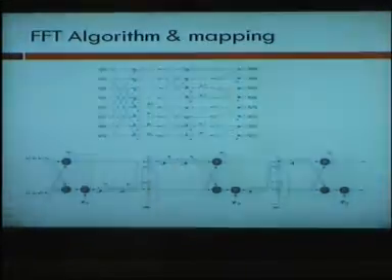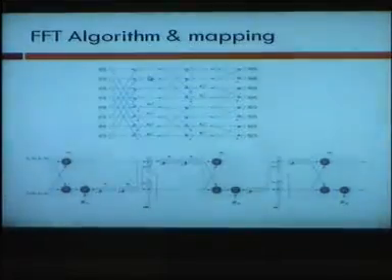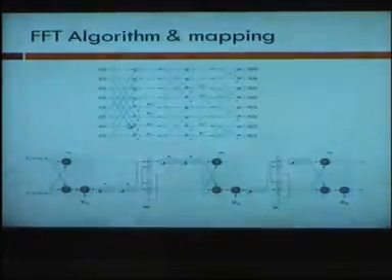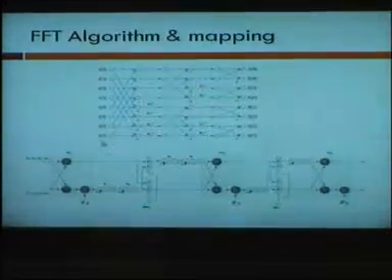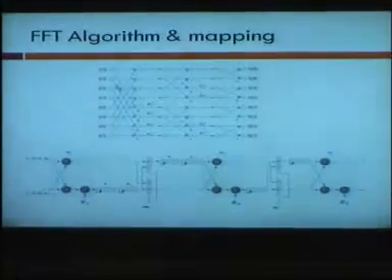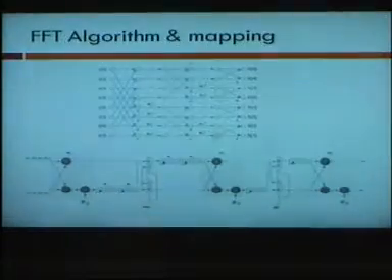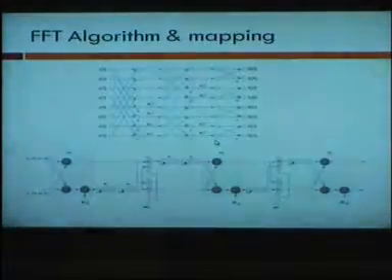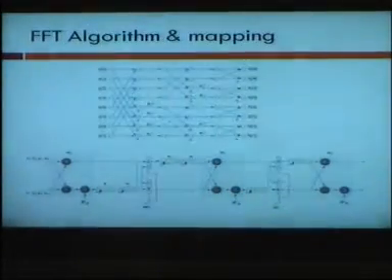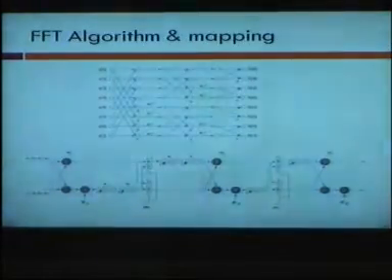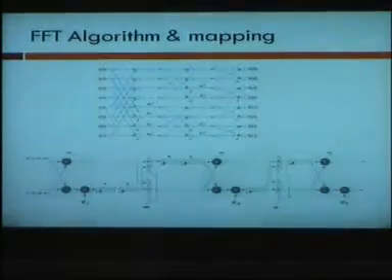So this is a flow graph of the fast Fourier transform, and this is a hardware implementation. It's a very interesting, not very easy to conceive design, where if you count, these are 1, 2, 3, 4 butterflies. And in every stage you have 4 butterflies. So if you're doing it in software, it's 12 butterflies.